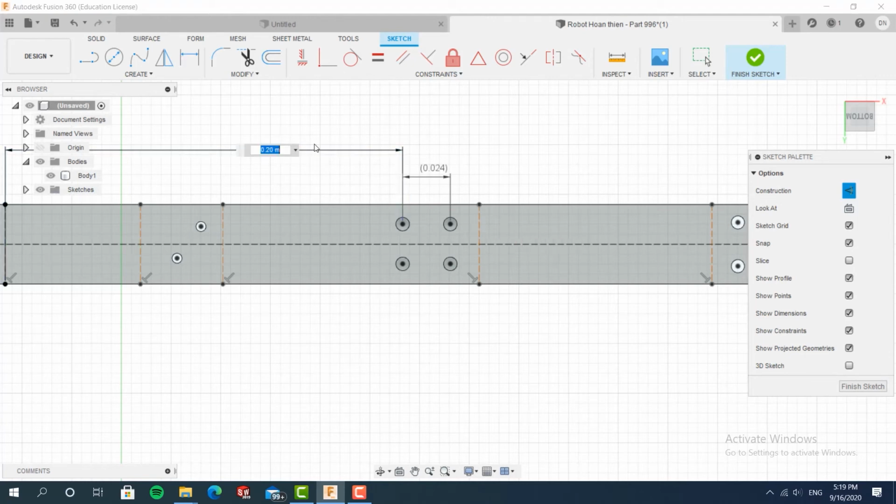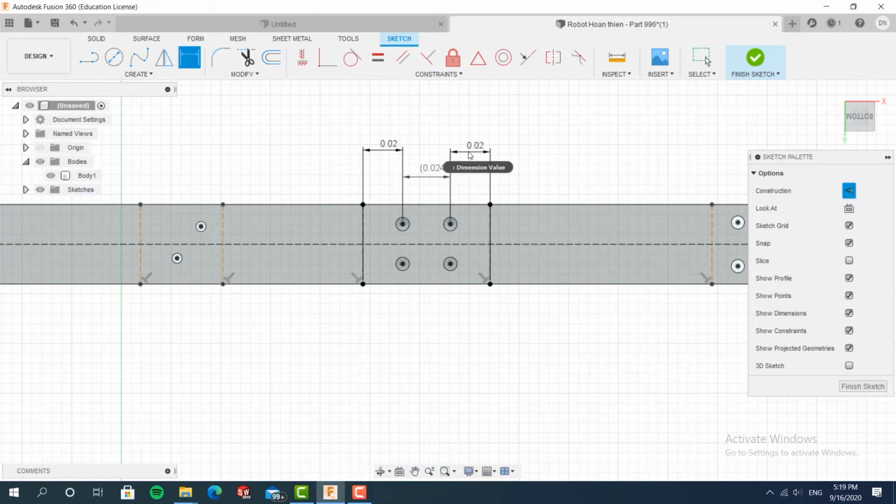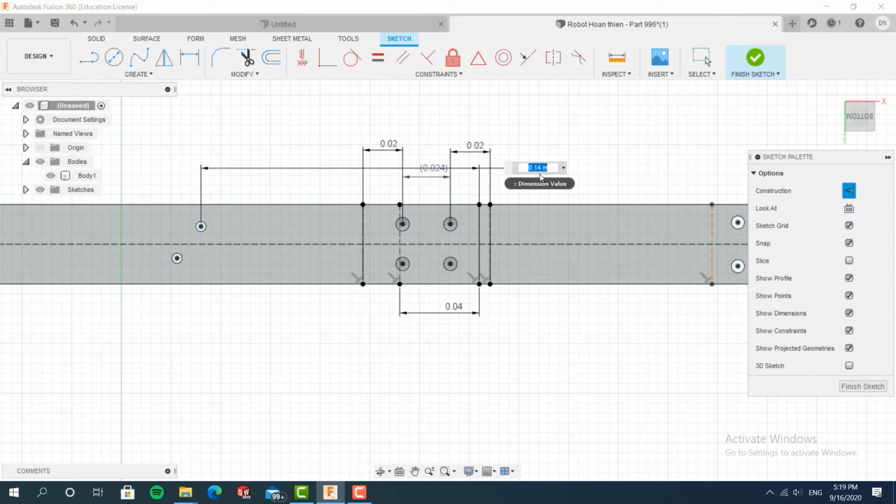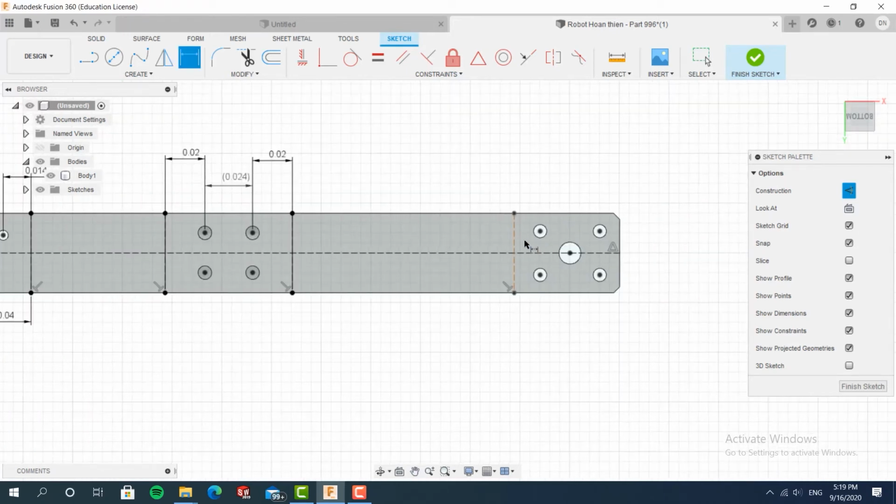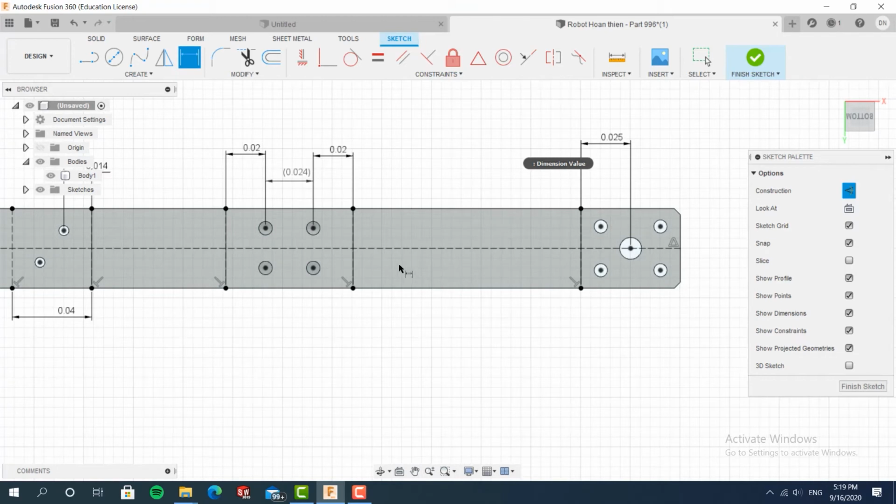First, the points of attachment with different parts. When you're cutting out things, you don't want to cut out parts that are too close to the holes that you're going to attach to different parts, because that will weaken the connection point. So first, you just zone out the area around all of the holes and attachment points. As you can see here, I'm drawing out some construction lines to just zone everything out. Then I can start drawing some actual circles.